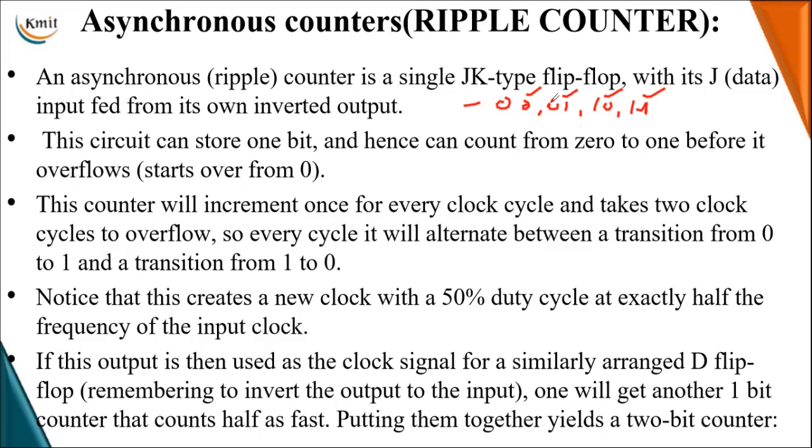So after every one count, the state of the flip-flop is toggling. Initially we have 0, then 1, then again 0 and 1. The input clock signal frequency must be divided, which generates the lower flip-flop outputs. Observing the second bit, for every 2 states the output changes. Such a design we have to follow here. Since the least significant bit is altered for every clock signal, we are going to use the toggling state.